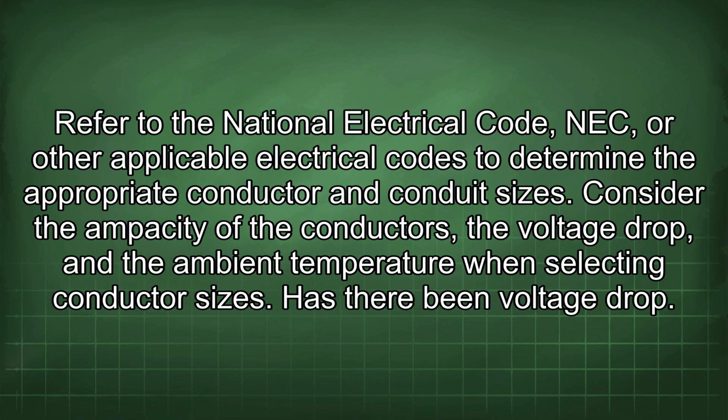Refer to the National Electrical Code, NEC, or other applicable electrical codes to determine the appropriate conductor and conduit sizes. Consider the ampacity of the conductors, the voltage drop, and the ambient temperature when selecting conductor sizes. Has there been voltage drop?